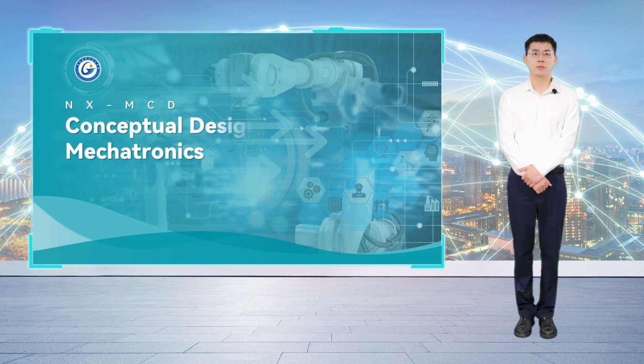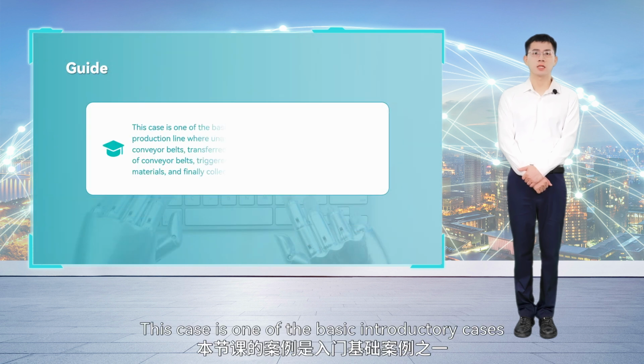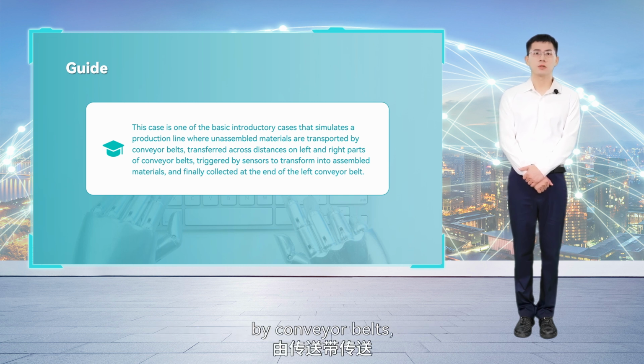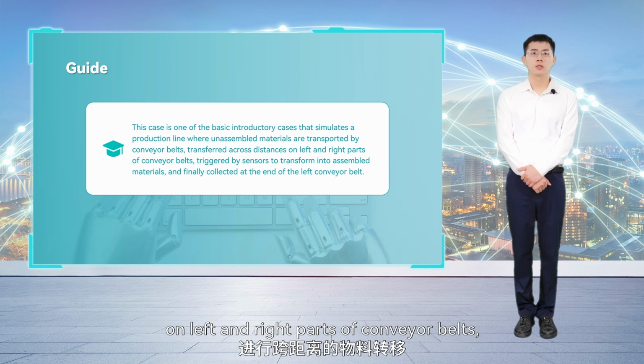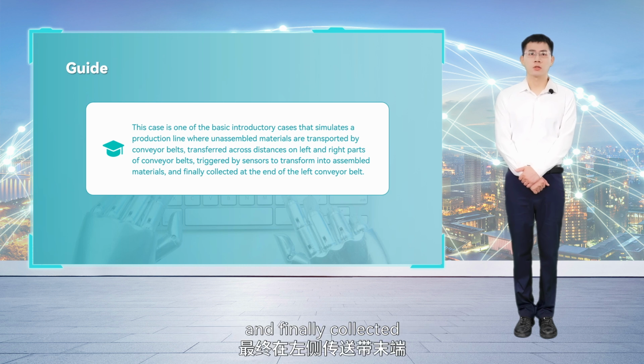Hello everyone. In this lesson, we will continue with the operation of the NX-MCD module. This case is one of the basic introductory cases that simulates a production line where unassembled materials are transported by conveyor belts, transferred across distances on left and right parts of conveyor belts, triggered by sensors to transform into assembled materials, and finally collected at the end of the left conveyor belt.